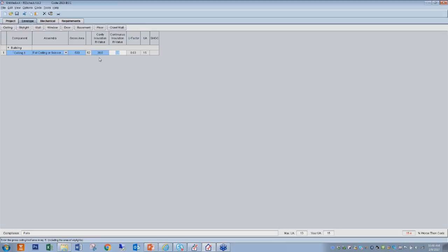Now, if you were to put continuous insulation in here for the ceiling, that's assuming full height, full credit, and it's typically foam board. And you're typically not doing that unless it's at the roof deck and you have a conditioned attic. So let's keep going.